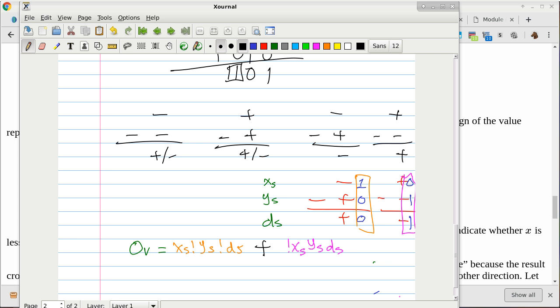So let me represent the problem, okay? We have the sign flag. The sign flag has the ability to tell you whether the minuend is less than the subtrahend, okay? So it can give you a binary answer. It is true that the minuend is less than the subtrahend, or it is false that the minuend is less than the subtrahend, okay? But it does lie from time to time.